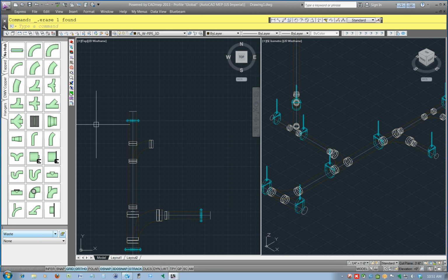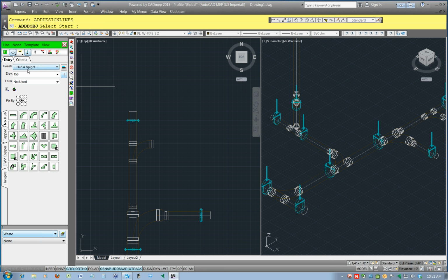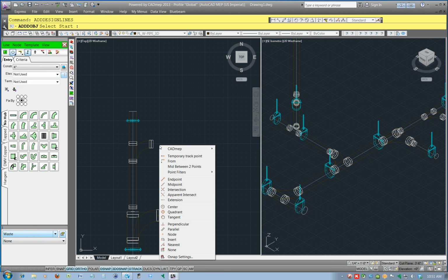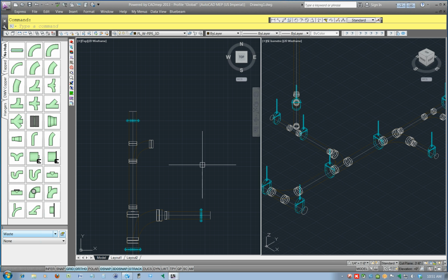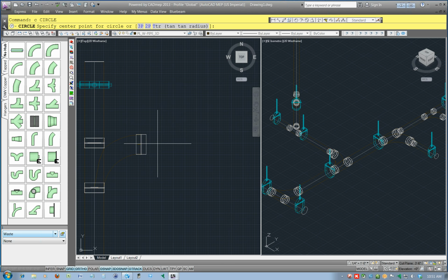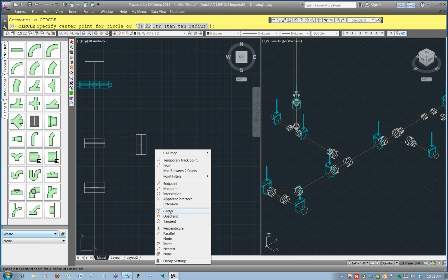Okay. Now I'll go back and create a new design line. Oh, I know that's 4-inch. Elevation not used. And I'm going to snap to, I usually snap to center. And, oh, they still have that turned off in this version too. I'm sorry, if you want to snap to it, it's not going to snap to the 3D object.